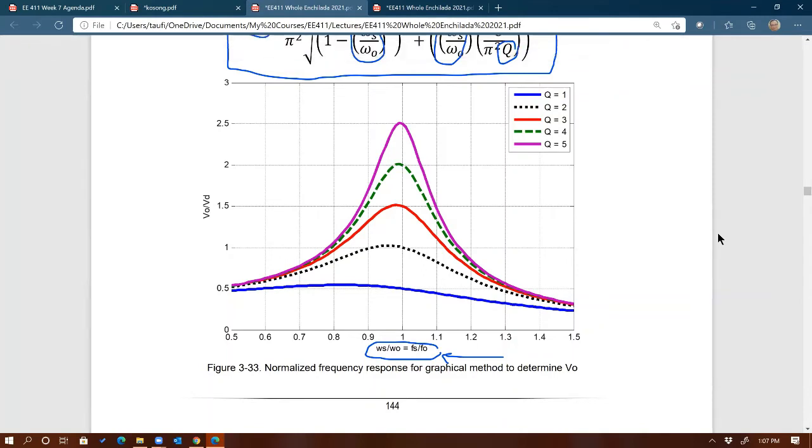Like just for the final project, I was looking around for transformers. Can you just use any kind of transformer, or are you looking for something special? Well, low frequency transformers are different from high frequency transformers. So for this type of application, you definitely want to look for high frequency transformers, because typically you would operate these at higher than 60 hertz, right? At least kilohertz type of switching frequency, right?